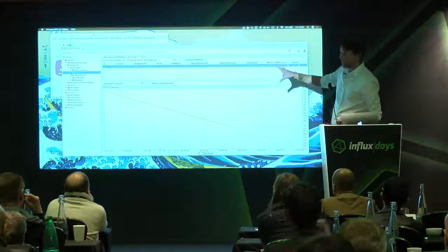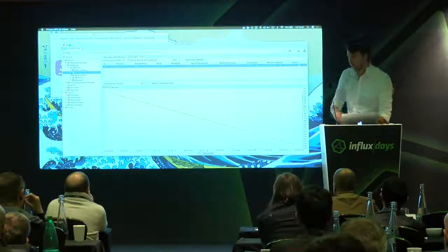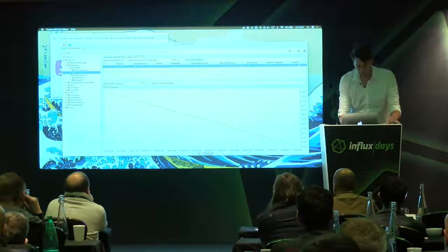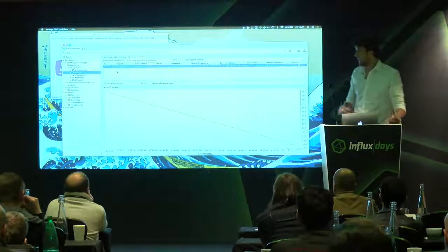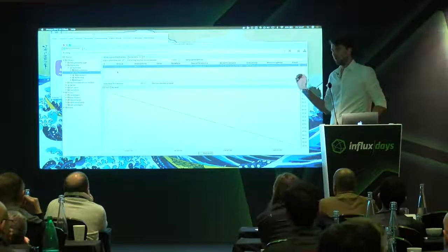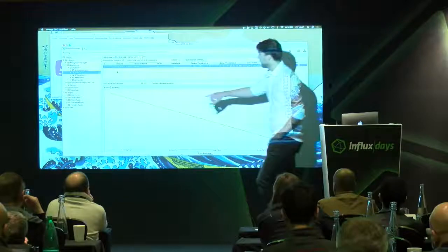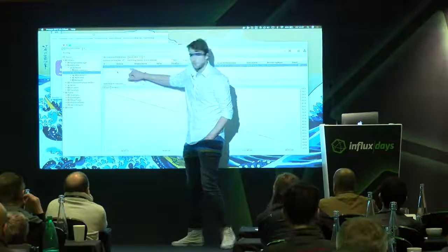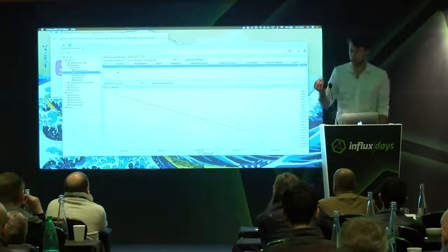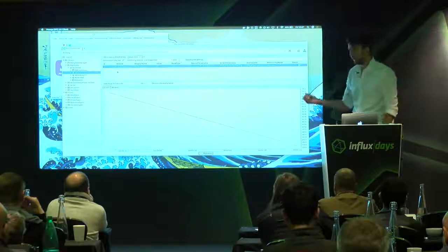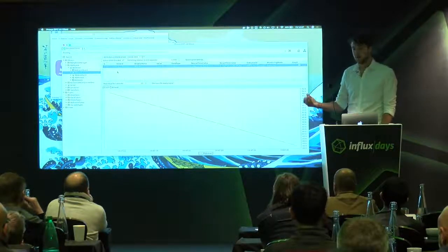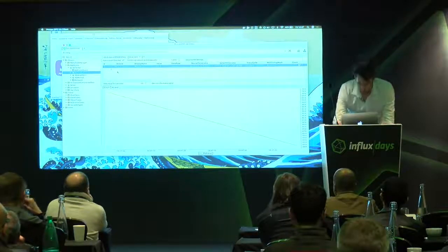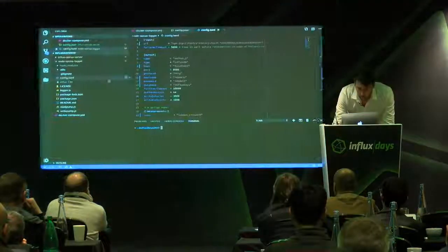So how do we get this data into Influx? We go to GitHub, we download our OPC-UA logger project, and then you need to identify all the nodes you want to collect data from. So you'll need the node IDs. These identify a single data point, a sensor value, a memory register in a controller, that kind of stuff.